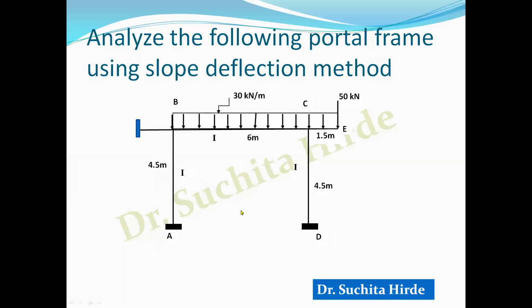Now let us consider this frame. If you draw axis of symmetry, it is not mirror image on other side. If anybody asks you whether it is a sway frame or non-sway frame, then first of all you have to look for whether there is such support which restrict the horizontal movement of frame or not. So you can observe here there is one support because of which there is no translation of the joint. So there will not be any horizontal movement in this frame and therefore this is a case of non-sway problem. So in this case also delta is 0.